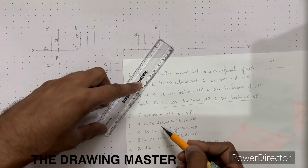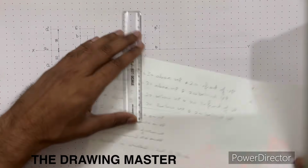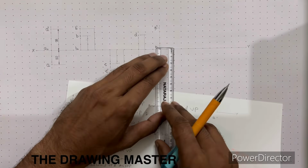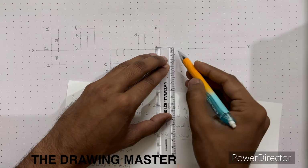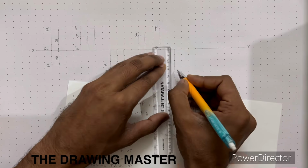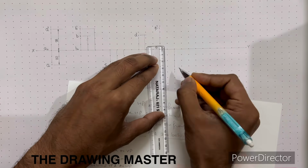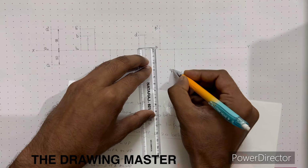Point Q is 30 below HP and on VP. Okay, so below HP means below the reference line. As we have seen, above and below is always front view. So label of the front view is Q dash.